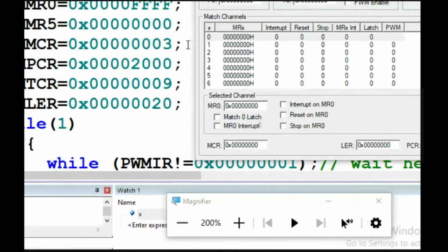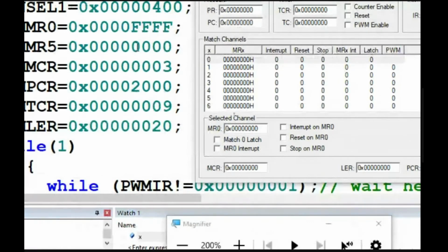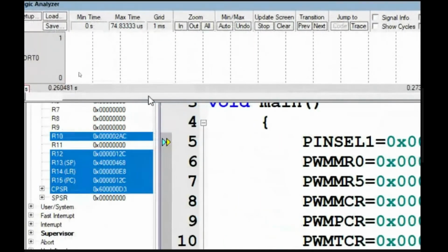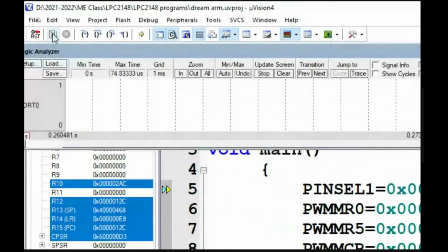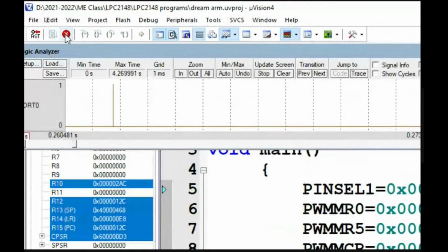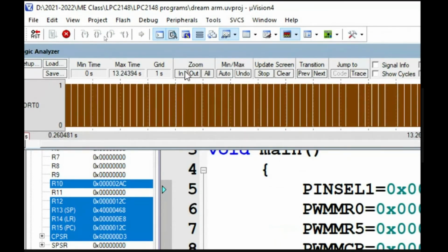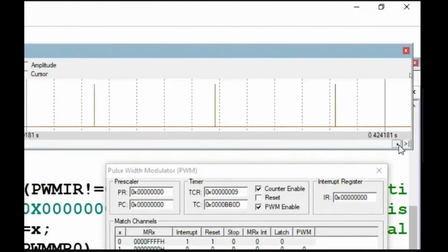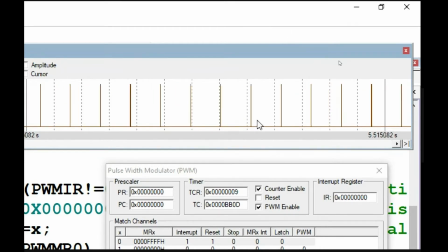Now you can see, it starts from 0 and goes up to 65,535. So I will get 65,535 steps between 0 to 5 volts if I run this code. That is what I have to do. So let me run this and stop this. It's very difficult. Let me stop this and then I can do it like this. You see, slowly 65,535 now. It will take much time, so let me reduce this and let me try.